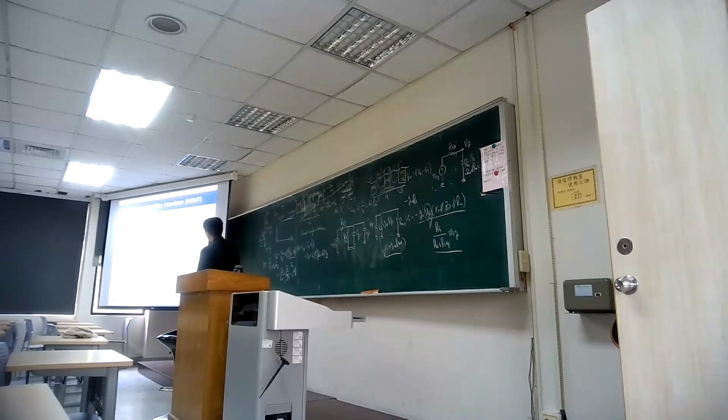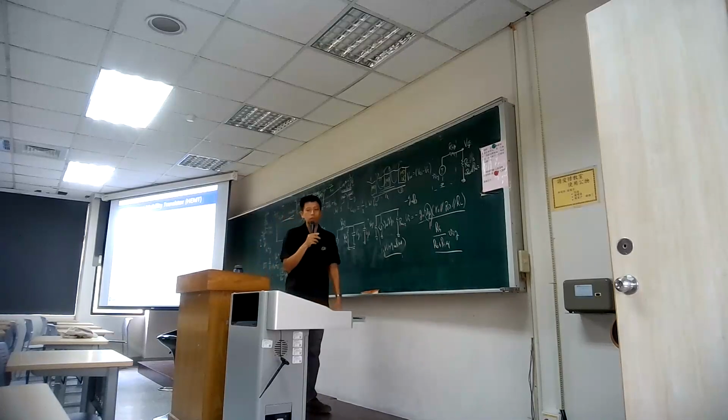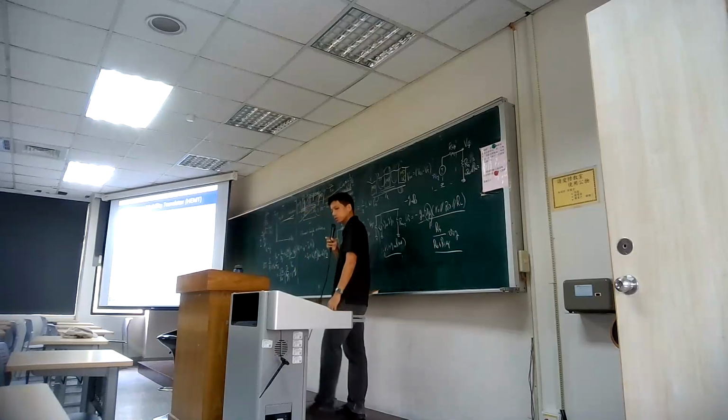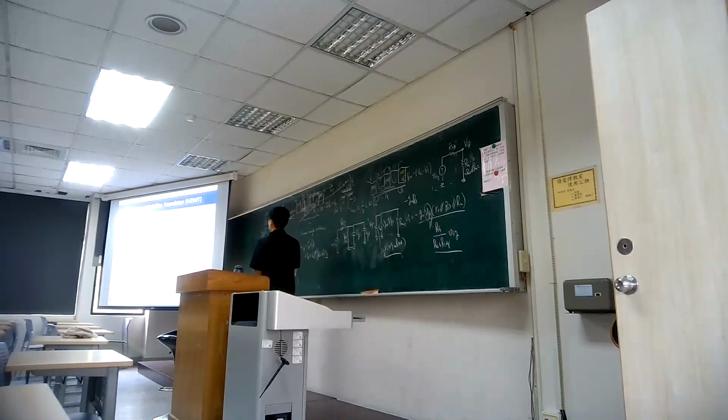So this kind of device can be used as a two-dimensional high power transistor. It is still based on the field effect transistor, which is compatible with the III-V material, but typically the dimension of your wafer is smaller compared with 12-inch, 300 millimeter technology. For III-V material, people in our lab only use 2-inch to 4-inch, maybe only 2-inch, because the epitaxy substrate is quite expensive. And then that will give you better conductivity for this heterojunction.